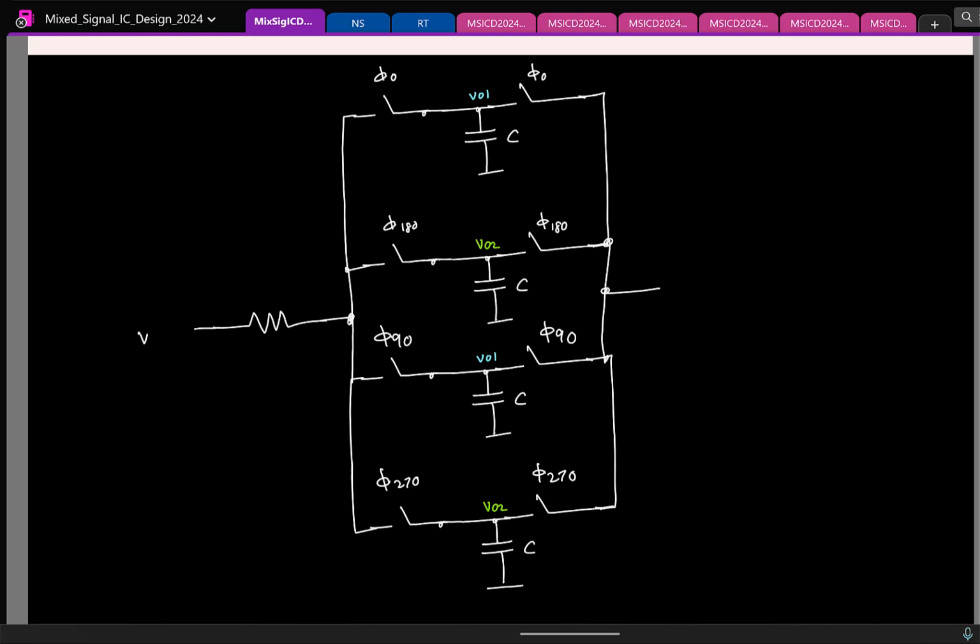All the resistors aren't active at the same time. Correct, exactly, that is also a point, because at a given point, only one of the branches is active. This is happening because the clocks are assumed to be non-overlapping. So this is in practice called the N-path filter. Again, this is a 4-path filter, and the generic extension is N-path filters.